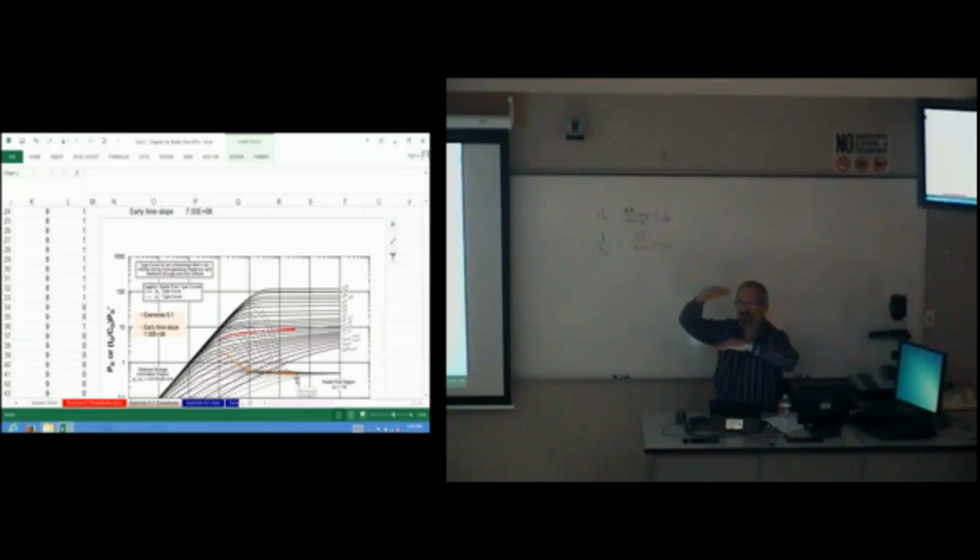Knowing perm, you should have been able to put the altitude of your red data, your derivative data, which looks like it's mustard yellow or something like that, on the graph. So there's only one variable that I really didn't know, because I don't have any data in my wellbore storage dominated region, the unit slope line.